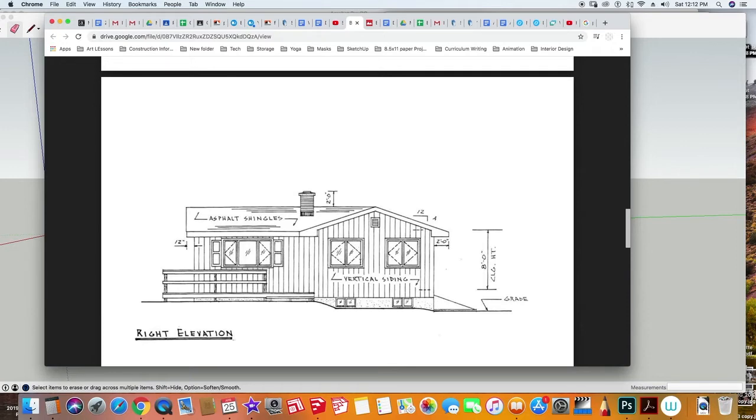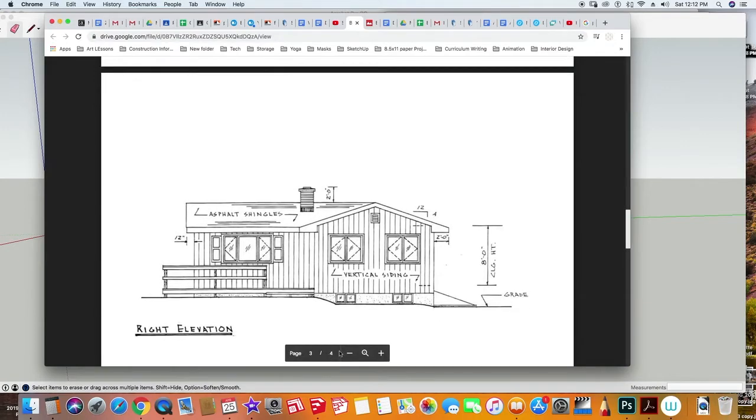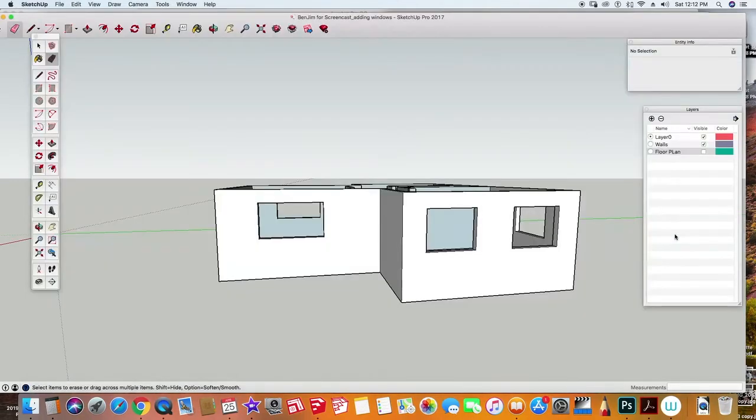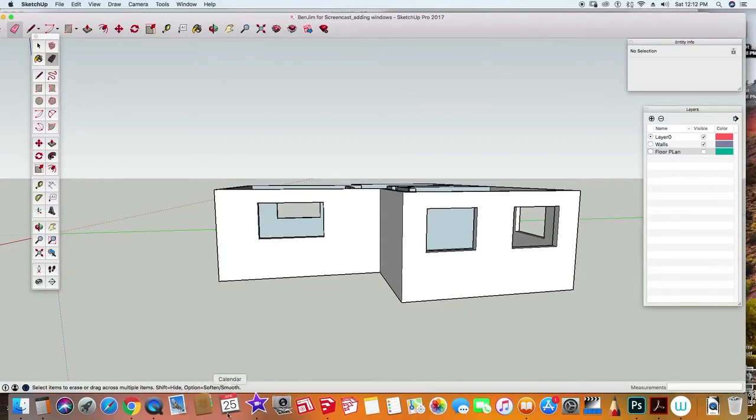Now in this case we're not making them open, so it's not so critical, but what I do want you to look at is that when you look carefully at this window, you'll see that there's an outer part of the window, which is the frame, and then another line that represents the individual rails and stiles of the 2 windows on the inside. So this is not simply a square or a rectangle with glass in it. There's actually some detail here that will make your model more realistic if you include it. So it's important to do that. That little extra detail will really go a long way.